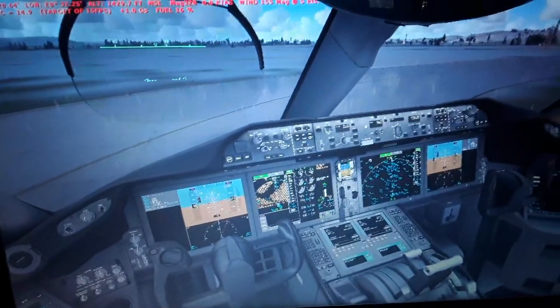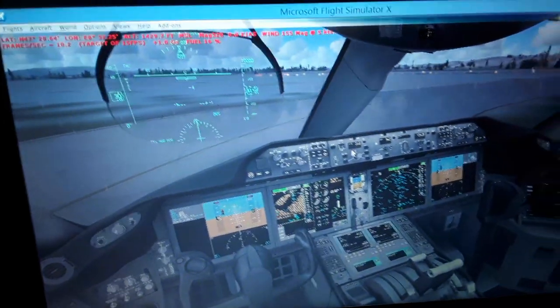And we have the onboard antennas of the aircraft that receive the radio frequency and display the horizontal localizer and the vertical glide slope. We can see the display in the primary flight display when we are configured for takeoff and for landing. So we have also the localizer crossbars. We have the flight director crossbars for manual guidance of the aircraft and the autopilot crossbars for automatic guidance of the aircraft. We have also the angle of attack of the aircraft as it flies, and the flight mode annunciator with the autopilot and the auto throttle modes, later on the vertical navigation modes.